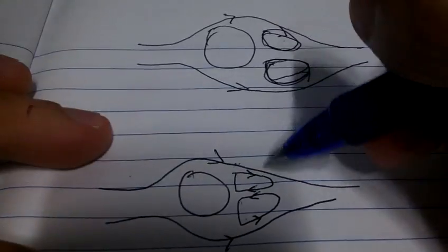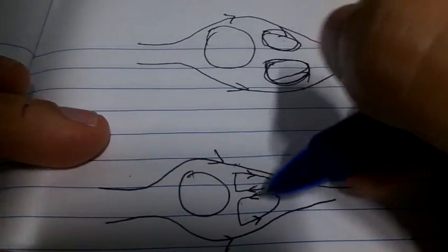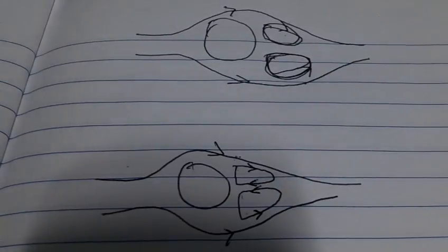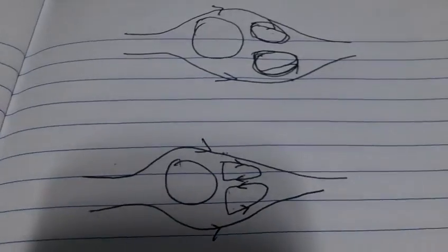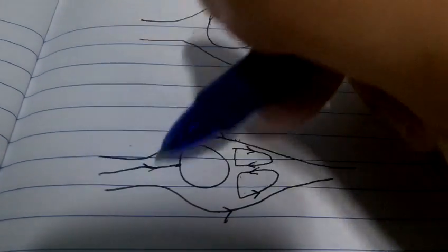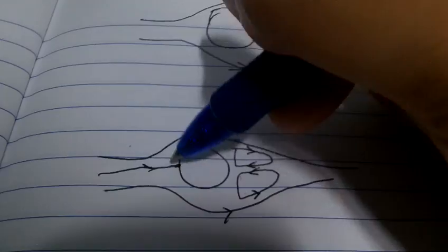As it turns around, it dissipates energy and causes a lot of drag, because this is a low pressure region and this is a high pressure region. Over here the fluid just stops, and this will be the stagnation pressure as it stops at this spherical object, and over here the pressure will be lower than the stagnation pressure.